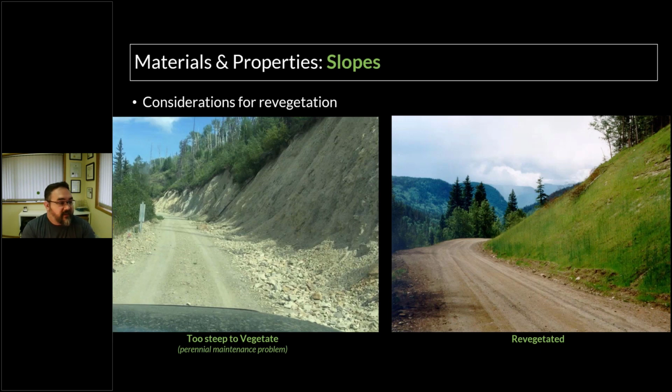Insloping of roads, swaling the grade so you're not concentrating flow over long periods. And then, of course, on a more permanent road, if you want to get that vegetation started sooner, you're going to cut that back to an angle where it's not going to actively ravel, so that vegetation can get a footing.